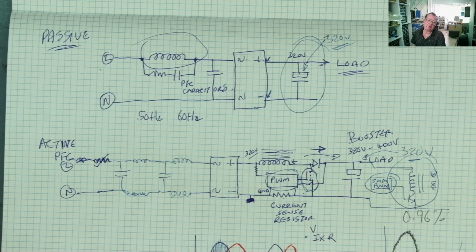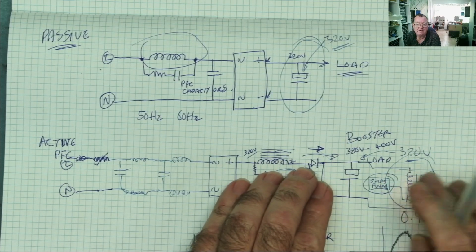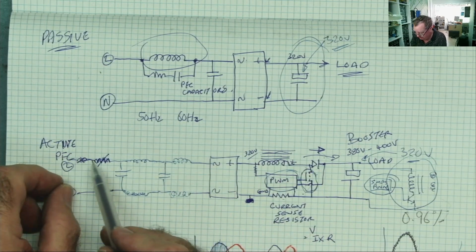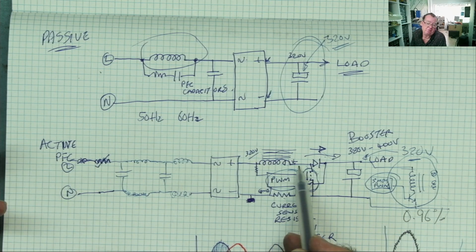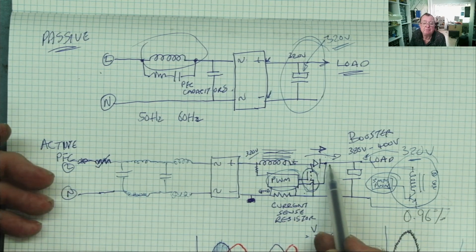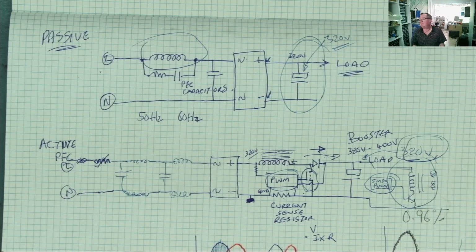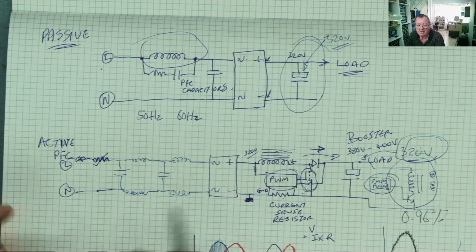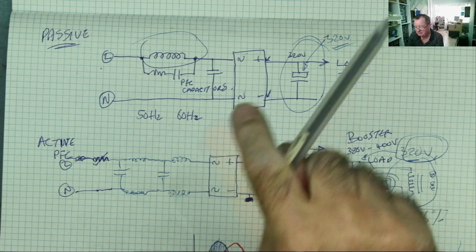What happens in this circuit? Well, again, if the PFC isn't running and the power supply isn't running, when we plug in, AC comes in, rectified to DC, straight through this piece of wire, effectively at mains frequency, straight through the diode, and the capacitor charges up to 320 volts, just the same. We've got 320 volts in the capacitor with no load on it. We unplug the power, there's nowhere for the 320 volts to go, so it sits there waiting for you. I'm waiting for you, okay?